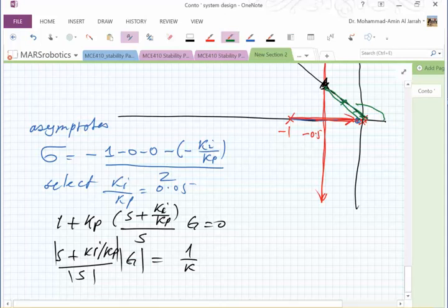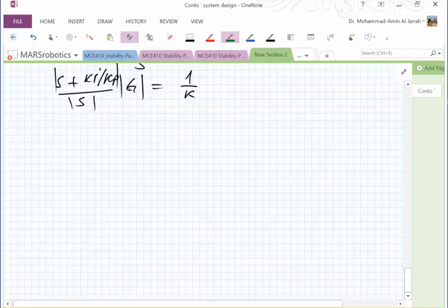When we maintain this difference in the angle small at the desired location, this also means that we are making their magnitudes similar. So their effect cancels out, and I get the performance of the system at the desired root location. And we can verify this mathematically. Professor, like this, we didn't only improve the transient, we improved the error also. So now let us look at the combined system.